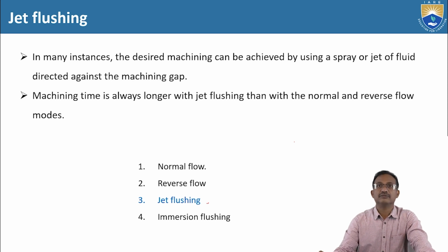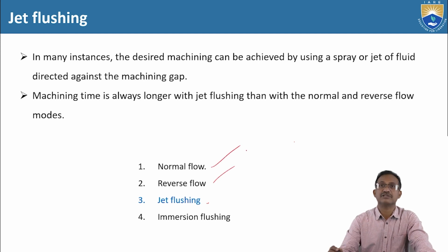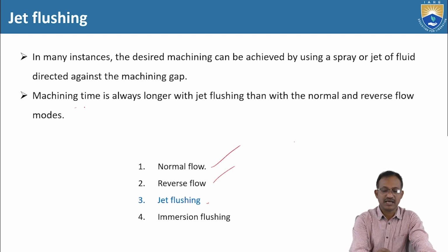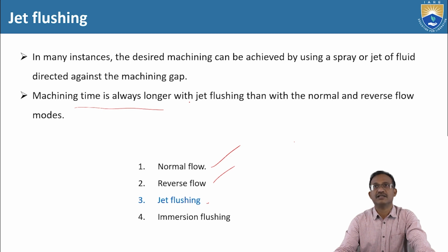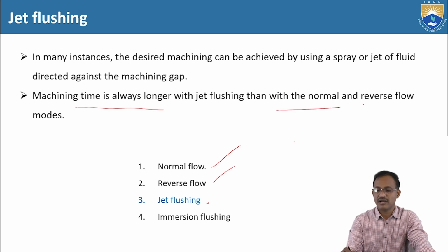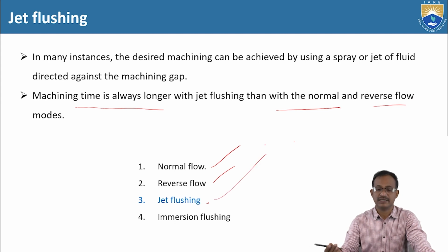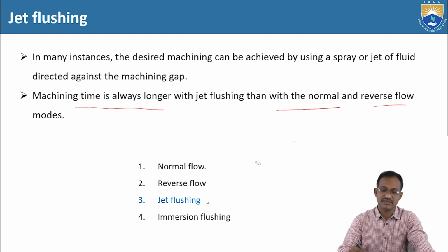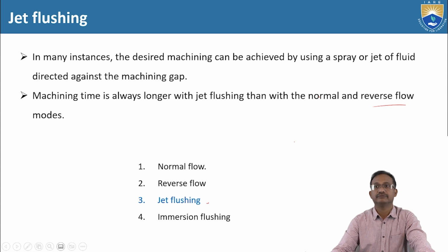Now let us focus on jet flushing. It is somewhat different to the above two, normal flow and reverse flow. Here the machining time is always longer with jet flushing than the normal and reverse flow. However, jet flushing will give good results, though the machining time is longer.